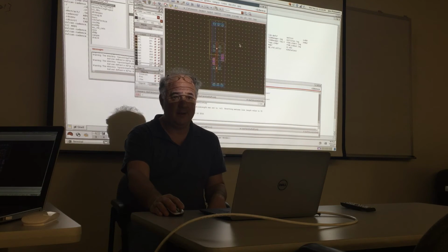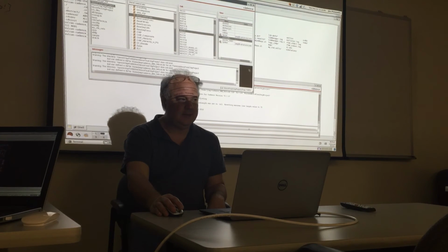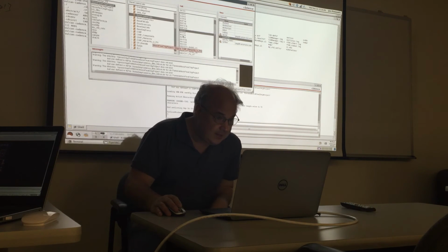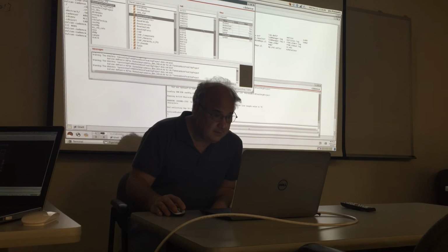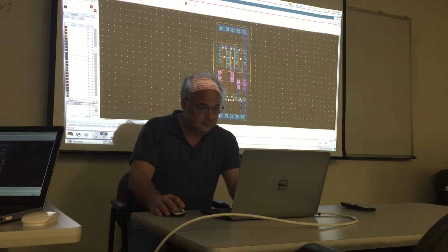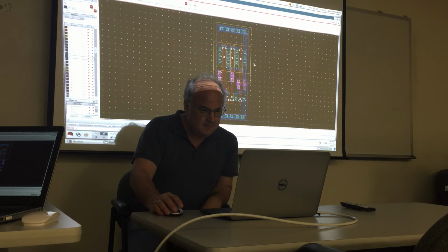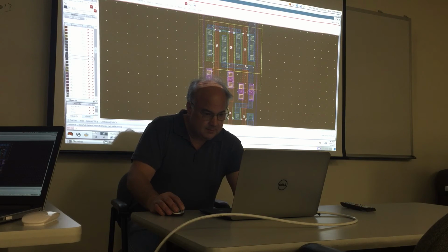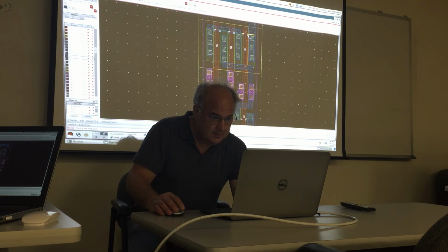You do? Okay. My AO, I don't have an AO. Not yet. You have an AOI though. I have an AOI, yeah. The AOIs are harder because I had to size all the internals. Do you want me to bring up AOI 1x? Yeah, this one, the layout. Okay, so why is your inverter's P transistor here not 1x? This guy? Yeah. It's not 1x? No. It should be 2x, right? And your infit is 1x.